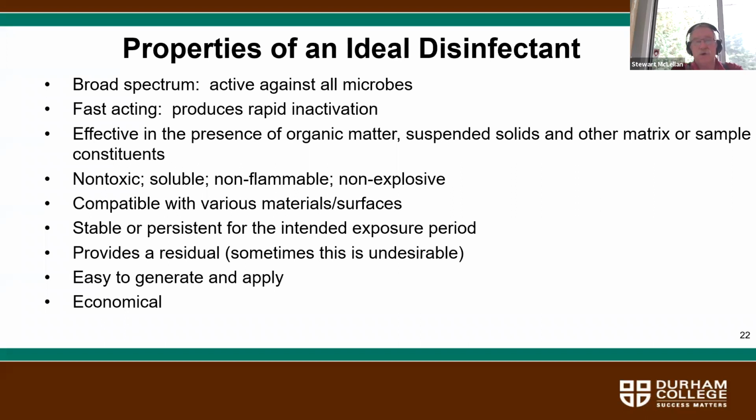So you have to make sure that you are adding your chlorine or your disinfectant at a rate greater than the demand of the water that's being treated. Ideally, it will be non-toxic, soluble, non-flammable, and non-explosive.